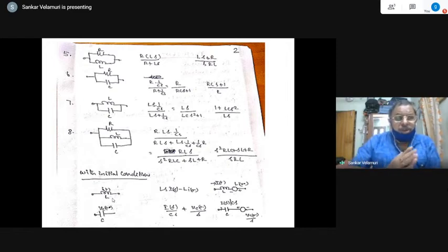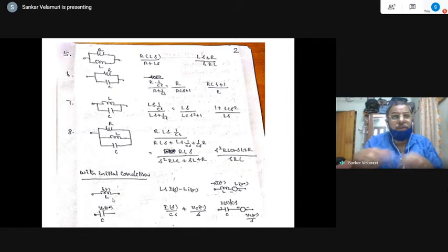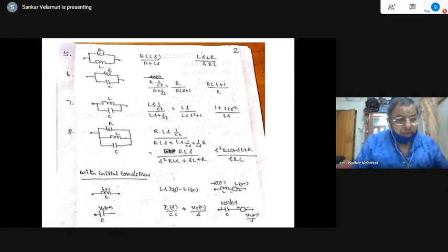That is why the transients are referred to as switching transients. The steady state current is available for the moment. Now we want to take off the supply. How much time does it take to die down, or for how long is the current flowing through the circuit? How much time it takes to die down implies that the energy is being retained in that particular storage element, the inductance, for a fraction of a second, or milliseconds, or sometimes microseconds, depending on the nature. That is the meaning of energy storage in this context.